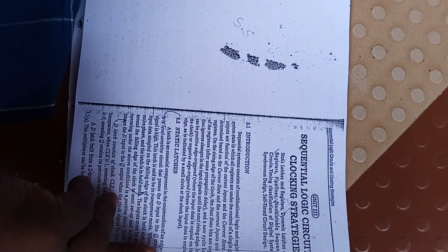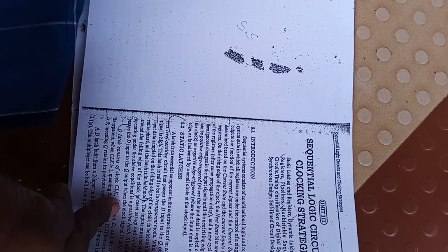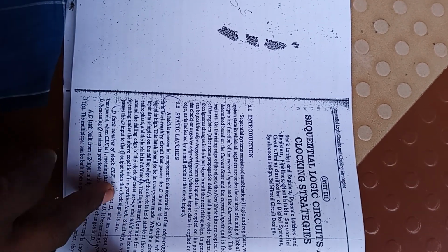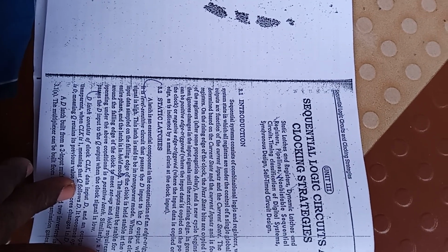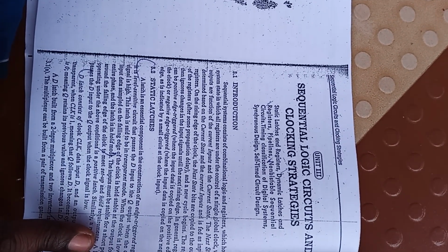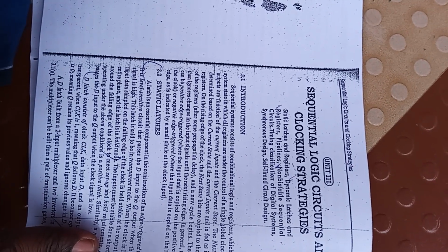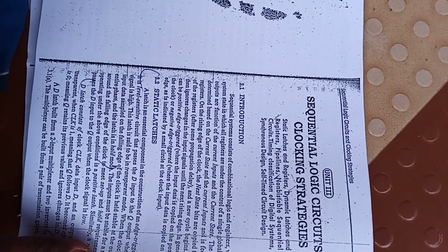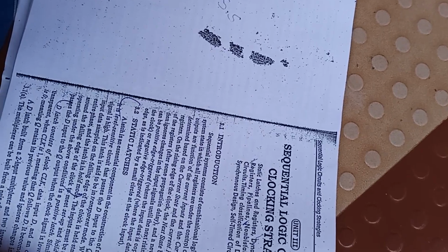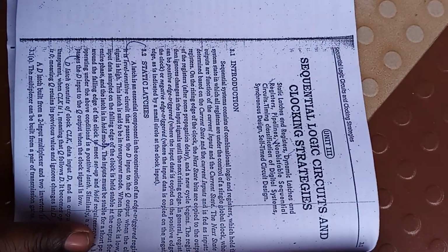So this is sequential in the sense that the next state depends upon the current state and the previous inputs. That means it must have a copy of the earlier states. That means it must have memory. So if the circuit is sequential, it should have memory as well as a feedback path, in the sense there is a path from the output back to the input. That we call a feedback path.